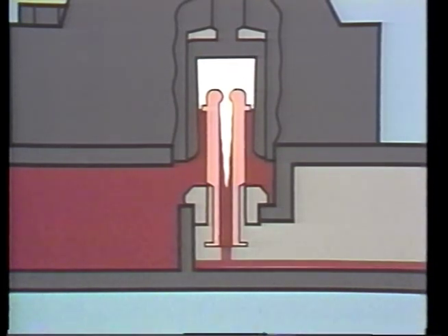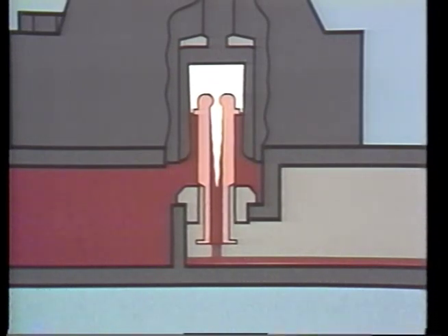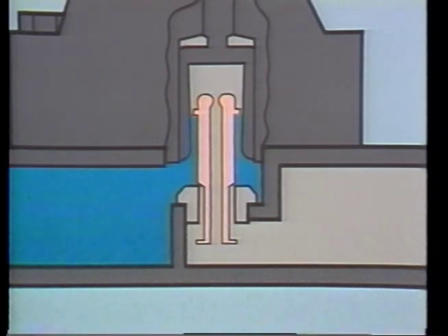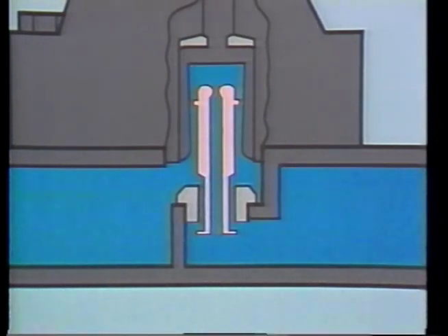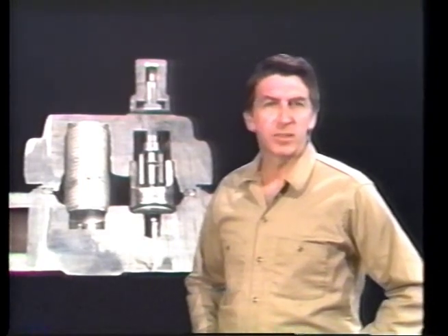Even with the piston shut, though, there is still control flow through the control orifice. The piston remains shut as long as the control flow of condensate continues to flash. When the condensate cools, the pressure above the disc drops and the piston reopens. Piston traps, like disc traps, are either open or closed, depending on the temperature of the condensate. This means their discharge should be intermittent rather than continuous.